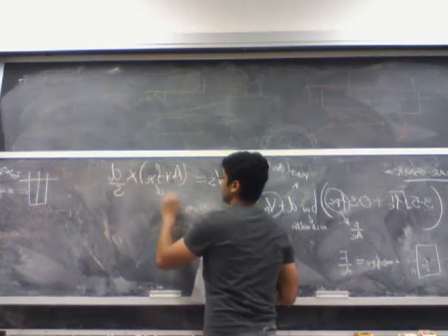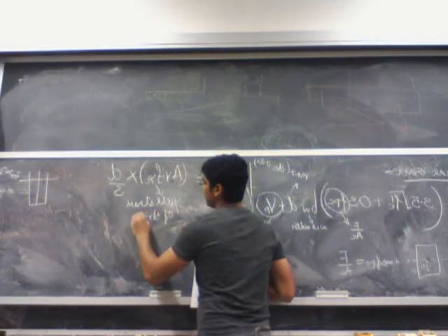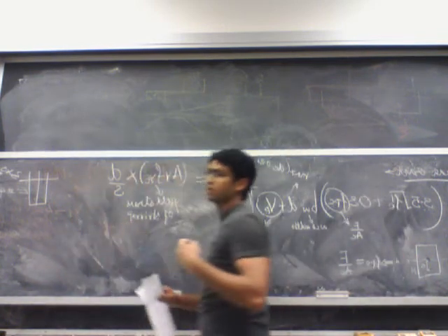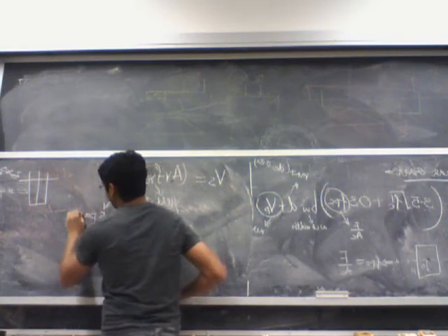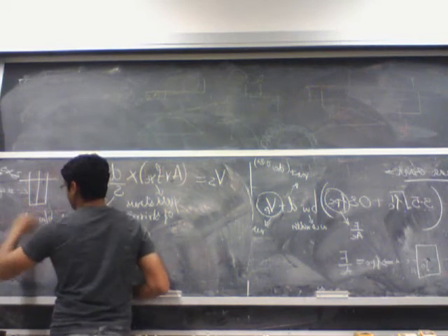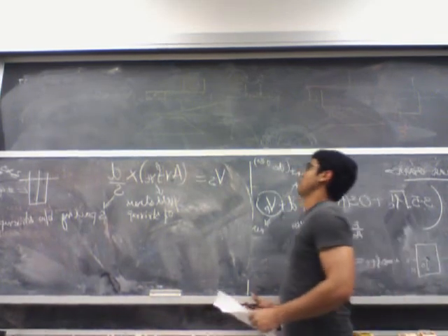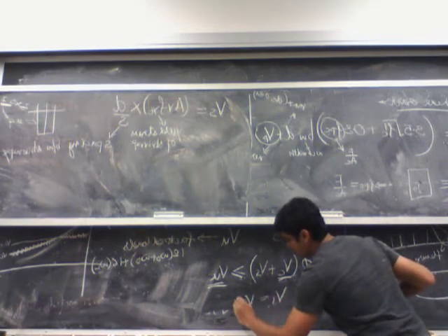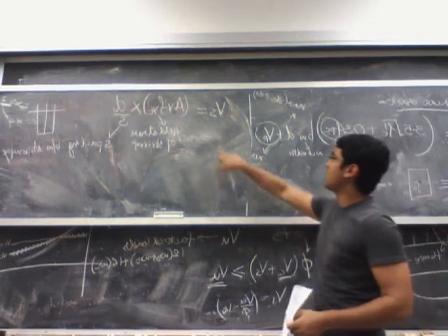fyt is the yield stress of stirrups. Again, we use 60 ksi. d again is the depth, d_e or 0.8 times h, and s is the spacing between the stirrups. So based on this formula, I can find the value of Vs as Vu over phi minus Vc. So I know how much Vs I need.